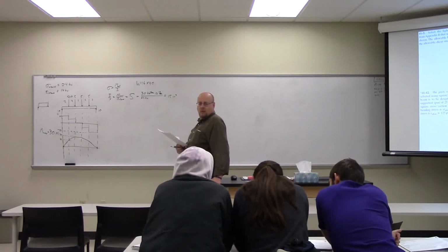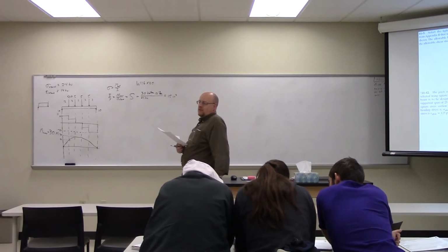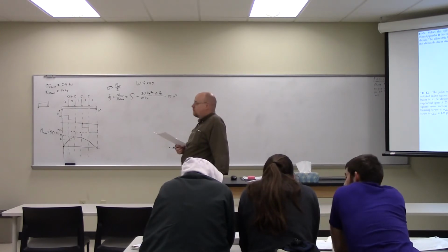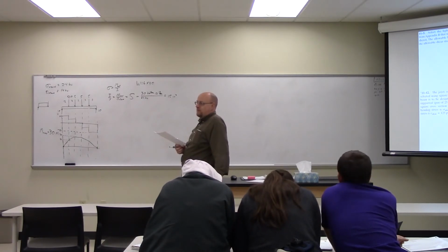Now, what direction are we bending? If you look in the table, you guys just have to remember this, so when you go back to your table, you will. There are two columns of S's and I's, one for the X and one for the Y axis. Looking at the picture, which axis are we bending it about? The X.